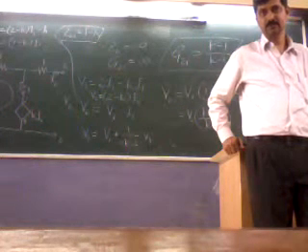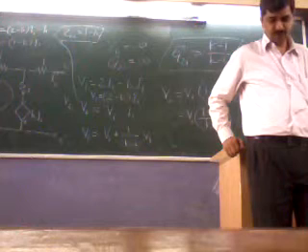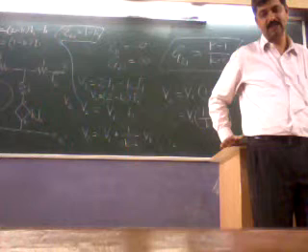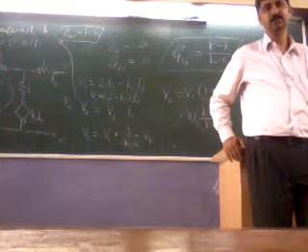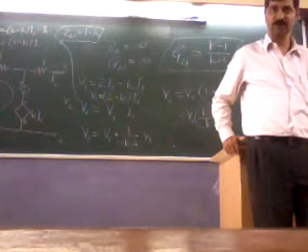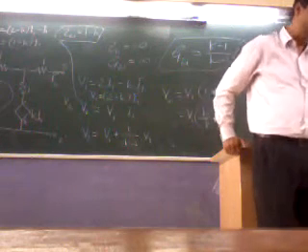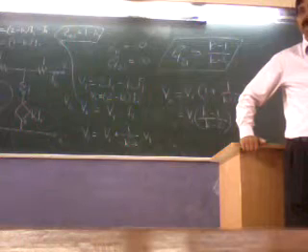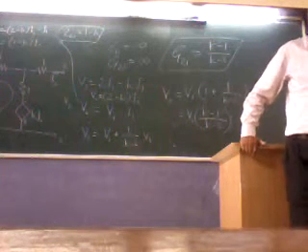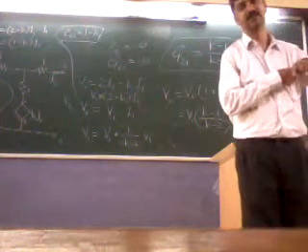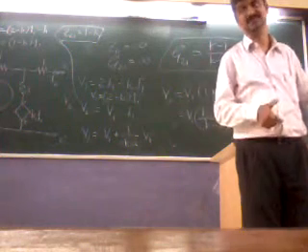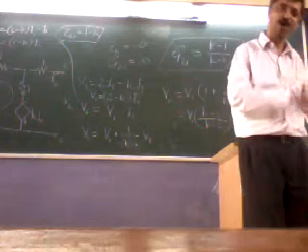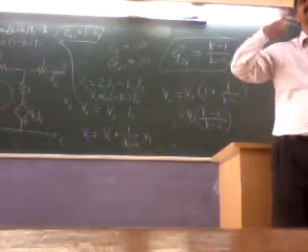Means even if the actuators are finite, if voltage or current somewhere becomes infinite, that means the network is unstable. In practice, this cannot arise because the dependent sources which we connect are themselves prepared using transistorized circuits or op-amp circuits, which are limited by their power supply.